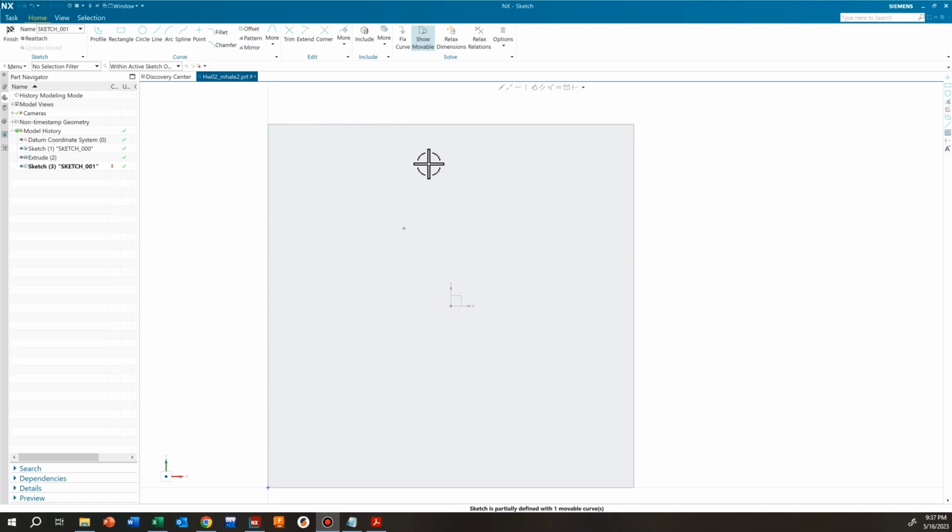Before, when we dimensioned the lines, we just clicked on them and gave them a dimension. We can't do that here exactly because we don't have a line to click on. We only have the point to click on. So what we want to do is click on the point, and then we can click over here on this axis, and a dimension pops up. Again, all I did was click on this point and then click on the axis, and a dimension popped up where we can do 0.5, hit enter. Again, it's going to ask us if we want to scale. Yes.